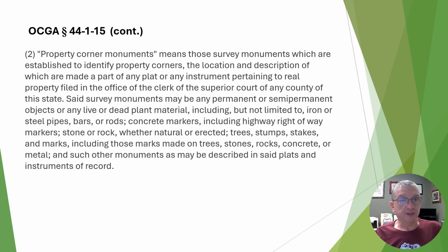But coming back to the law, it says, said survey monuments may be any permanent or semi-permanent objects or any live or dead plant material, including but not limited to iron or steel pipes, bars or rods, concrete markers, including highway right-of-way markers, stone or rock, whether natural or erected, trees, stumps, stakes, and marks, including the marks made on trees, stones, rock, concrete, or metal, and such other monuments as may be described in said plats and instruments of record.